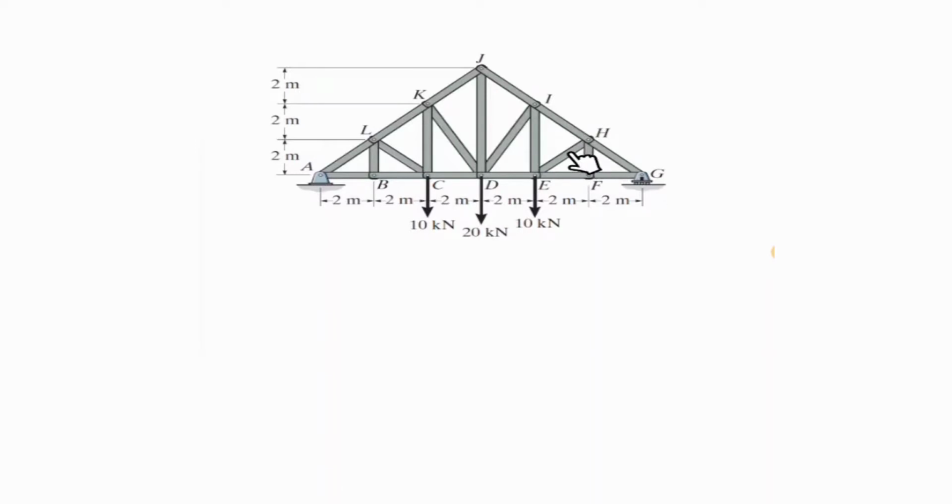And for example, if you know this and these are zero force members, meaning that you deleted two links at the beginning and you don't care about those, and you can assume that your structure doesn't have those links, and those links are ignored. And that would be very helpful in solving the trusses, because in many cases we are facing a great number of links, and deleting some of them can be very helpful at the beginning. And that's the first thing that I try to show you how to find.